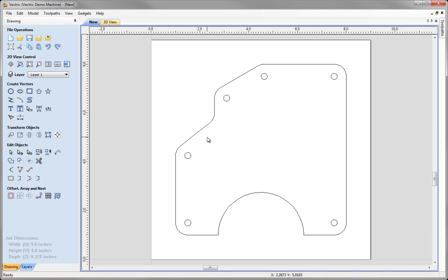So you can see there we were able to remove the fillets. We went in with the node editing in order to cut that part of the line out. We moved it across using the software's ability to do a calculation within the form. Then we used the extend tool and then trimmed it back and added the fillets and recreated the new position for our drill hole.